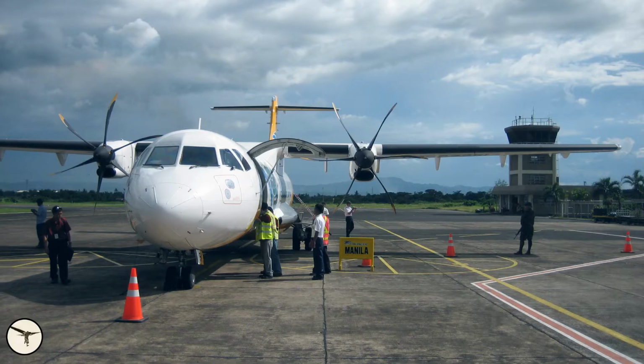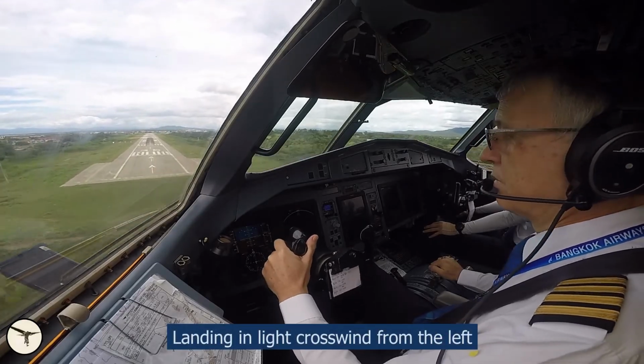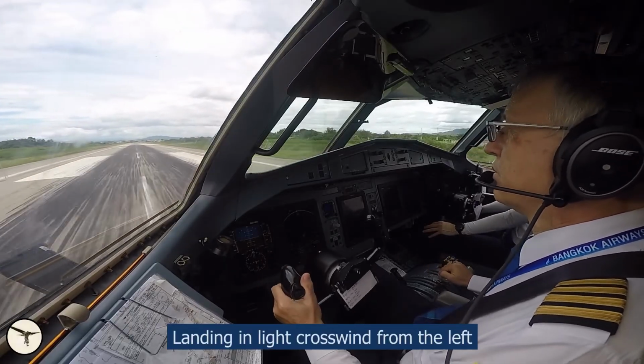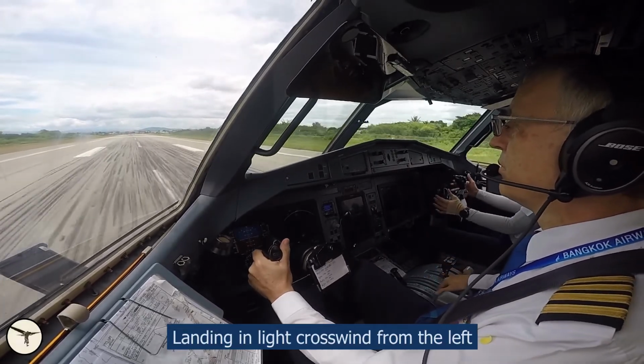I want to say some words regarding the use of ailerons during takeoff and landing in crosswind. The ATR has a high aspect wing mounted high up. This, together with a narrow landing gear, means that the aircraft is sensitive to crosswind. It is imperative for directional control that the wings are kept level in crosswind at takeoff and landing. If the crosswind component is 7 knots or more, and you don't use the ailerons correctly, your directional control might be compromised. The amount of aileron deflection depends on the crosswind component and the speed of the aircraft.